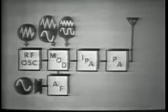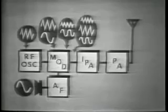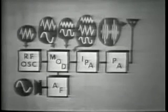When modulating 100%, each sideband voltage is only half as great as the carrier voltage. The audio frequency is not developed in the output because the RF resonant circuits have a very low impedance to audio. The RF carrier and its sidebands are coupled through the RF tuned circuits to the antenna. So we transmit these three frequencies: the carrier, the upper and lower sidebands, in a composite waveform.